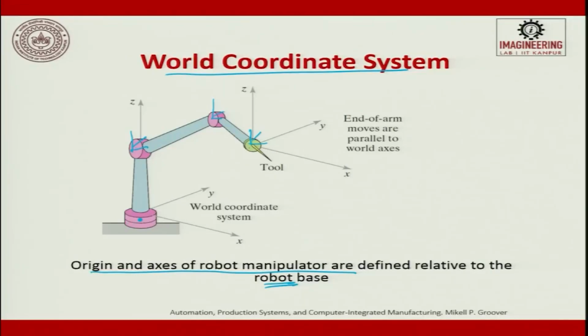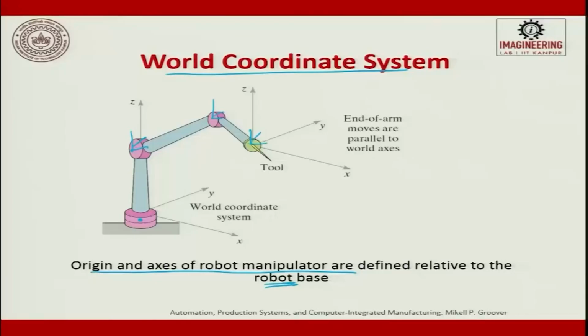At each joint you should be able to put a reference coordinate system, find out the XYZ axes, put them properly, and then start writing a program. In forward kinematics, we bring in all the translations and rotations about the axes, map them with the world coordinate system, and then execute the movement.